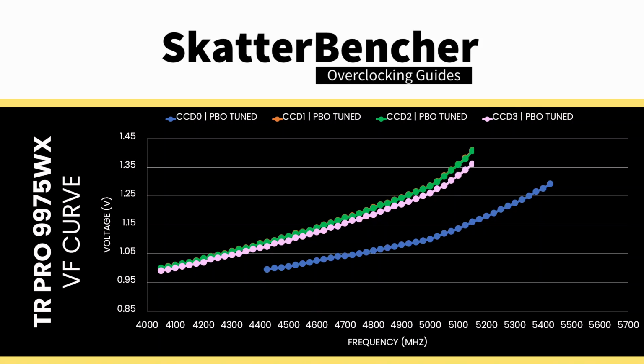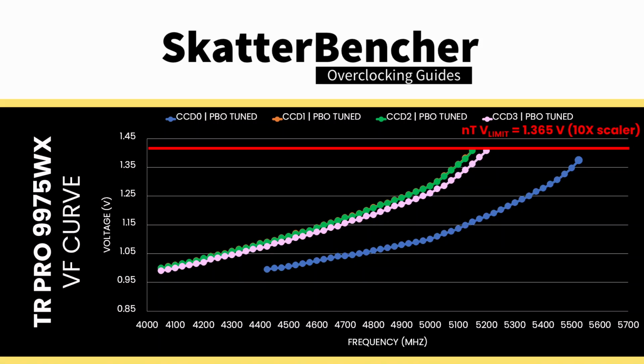That further extends the default VF curves to 5650 MHz for CCD 0 and 5250 MHz for CCD 1, 2, and 3. Note that all the other Precision Boost rules still apply. So even though we have a higher frequency ceiling, because some frequency points are above the voltage threshold, we won't see those frequency boosts in all core workloads, however light they may be.